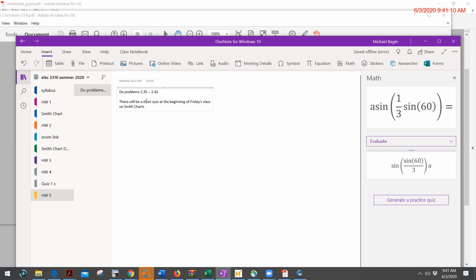Now, I'll tell you what I expect you to do: have a compass, a straight edge, and a calculator, of course, and you want to do all your work on the Smith chart and clearly label points 1, 2, 3, 4, and then draw the circuit out and put the lengths right on the circuit. Draw the load, then the transmission line, and indicate the length from the load to the point where you're going to connect either the short circuit stub or the element. It might be a capacitor or inductor, and show me a drawing of that either in series or parallel. And remember, shunt is parallel. You all with me on this, class?